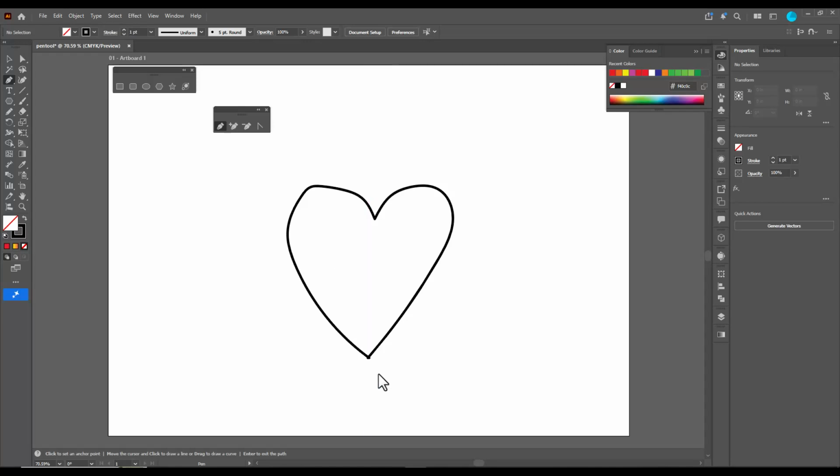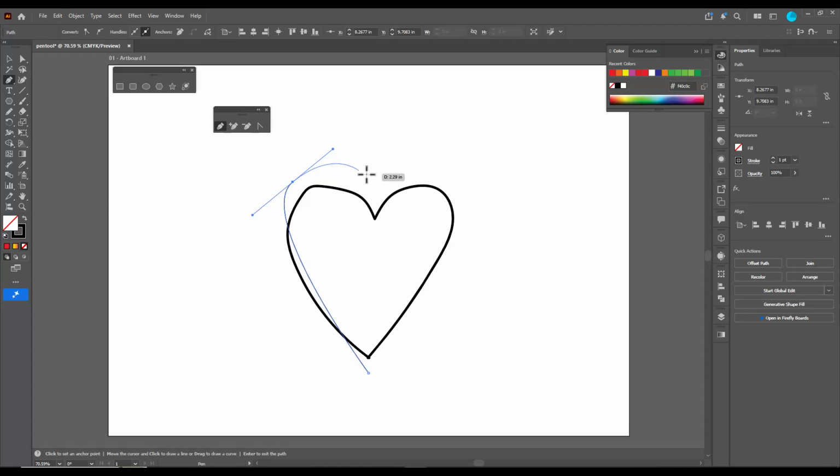So this is the sharp corner. Now we will click at the sharp corner, and then we will just drag near the rounded corner. While dragging we need to check the angle in which we are dragging, and we have to drag immediately, and we should not release our mouse till we complete our dragging. Once the dragging is completed, now we can release the mouse, and then here we have the sharp corner.